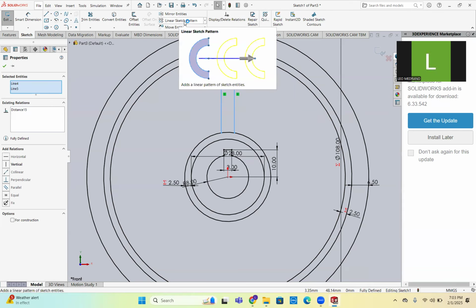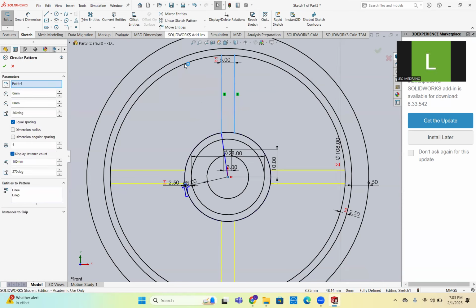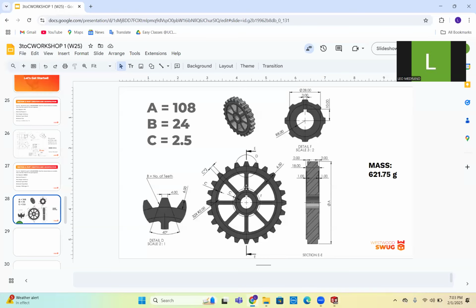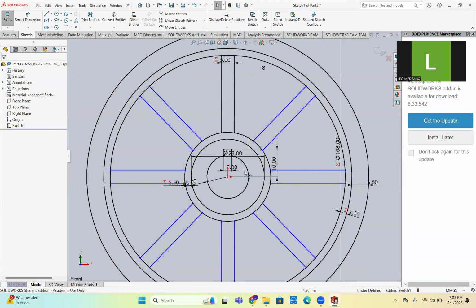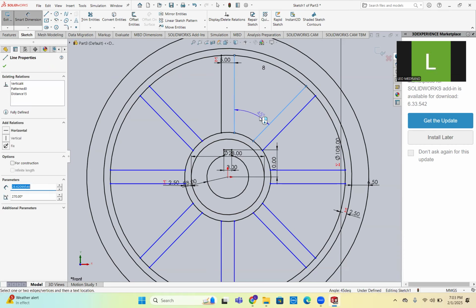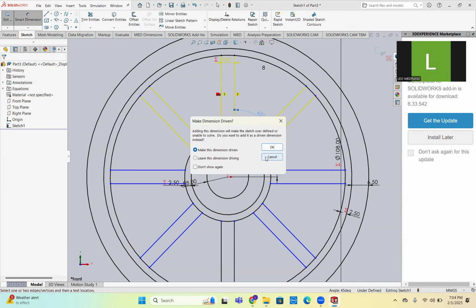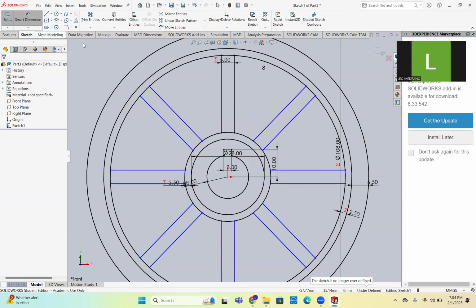Now, what you can do, if an option, which I don't recommend, but I'm just going to show, is you can do these options of like linear sketch pattern. There's a drop down. You can do circular sketch pattern. We know that there's a total of 8 pillars because we can count 1, 2, 3, 4, 8. So we'll just type in the 8 here. Awesome. You see, like you can do that, but these aren't defined. And what makes this annoying is you're gonna have to like play around to try to figure out that angle, like here, here, but it's overdefined because SolidWorks automatically knows that when you chose this circular sketch pattern, you chose full 360 and the amount it does.